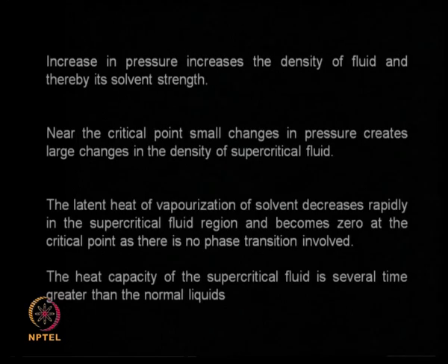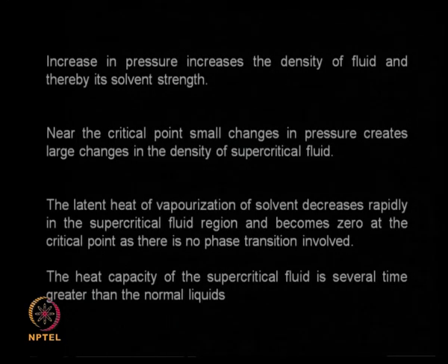So if I have a solid natural product and I want to extract the flavor or fragrance from that, then it can penetrate through small pores and then extract the flavor or fragrance. And also because it has got a low viscosity, the flow properties are also extremely good when compared to a normal liquid. So increase in pressure increases density of fluid and thereby the solvent strength also. Especially near the supercritical point, that is called the critical point, even when you change the pressure a little bit, you see large changes in the density of the supercritical fluid.